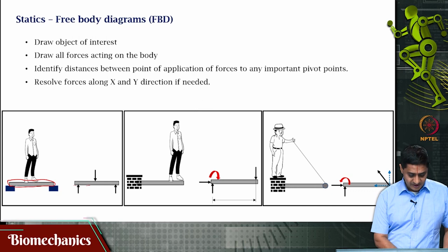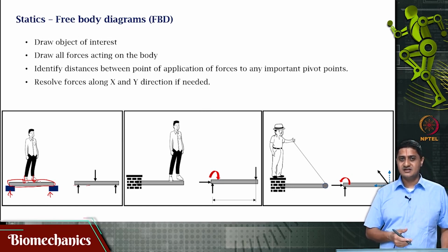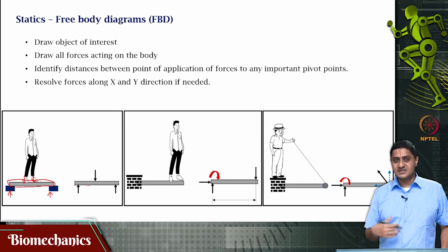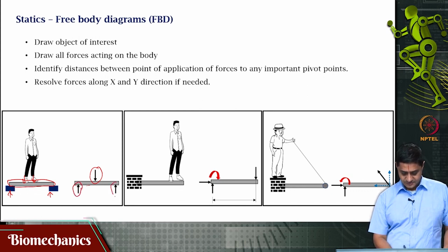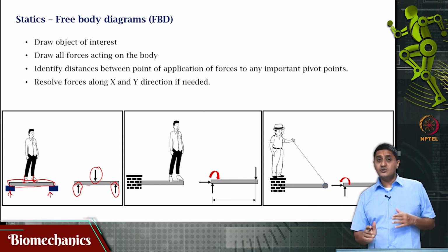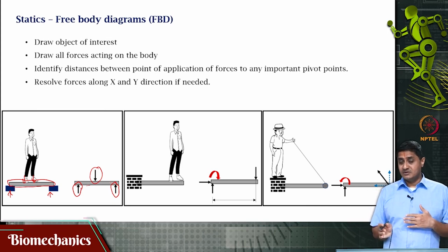Well, technically the free body diagram will have one force here, one force here and two forces here for the two legs, but I am assuming that these two forces of the legs produce a resultant that can then be represented like this. Okay. So, I have this as the free body diagram. This is the resultant force due to the person's weight, and the forces from the bricks are these two. Note that depending on where you are standing on the plank, the force from the bricks may or may not be equal, and that makes sense, right.